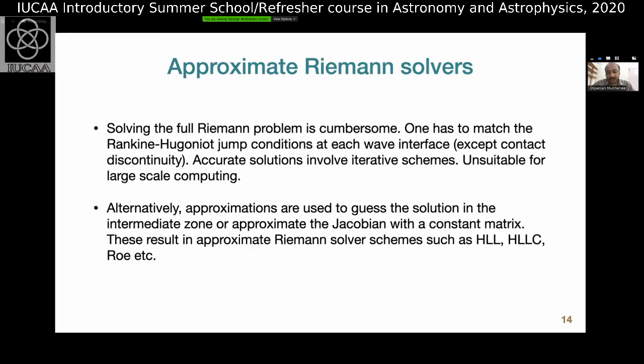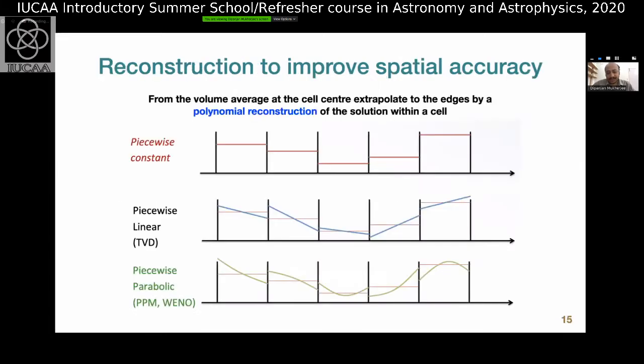Once you solve the Riemann problem, there is another piece of thing that you can do. As I said, in this way of defining things as volume averages, what you end up doing is you assume things inside this cell are just represented by one spatial volume average quantity.